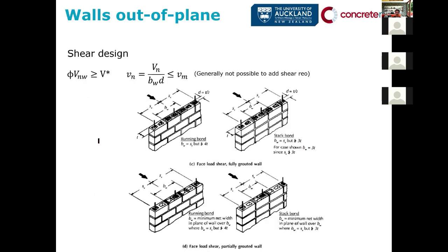Now the shear design is a little bit more complicated. On one hand, because we have more options, we can have running bond fully grouted or running bond partially grouted, and we can have a stack bond fully grouted and stack bond partially grouted. So this is a little bit more complicated. We have more options for the effective width of the wall.